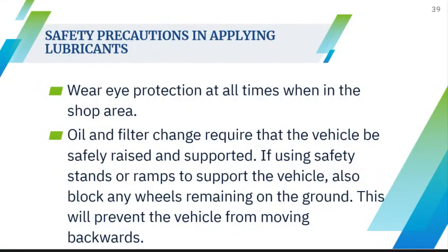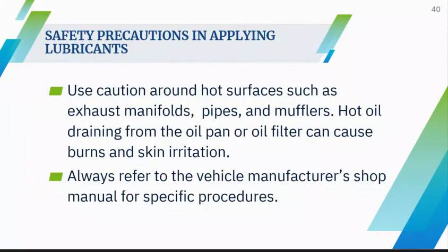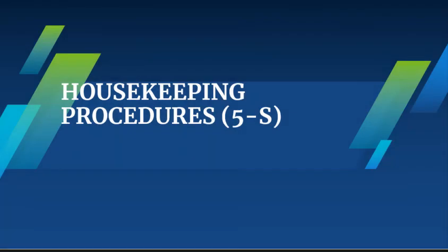Then safety precautions in applying lubricants. You have to wear your PPE, especially your eyewear. Oil and filter change require that the vehicle be safely raised and supported. Also, use caution around hot surfaces such as exhaust manifolds, pipes, and mufflers. Then always refer to the vehicle manufacturer's shop manual for specific procedures.